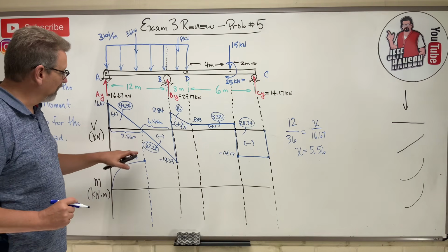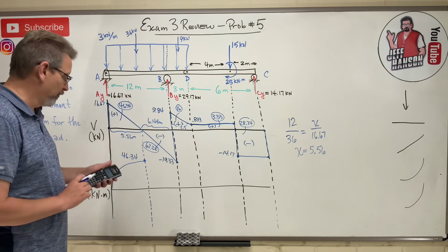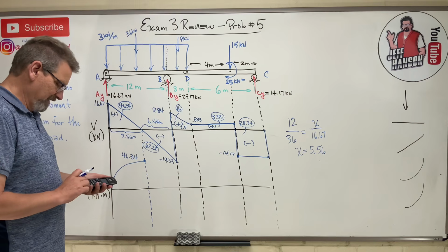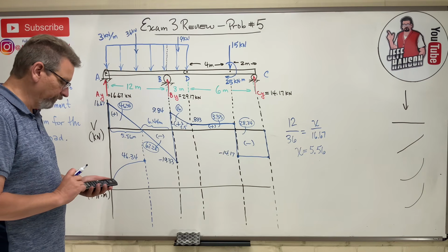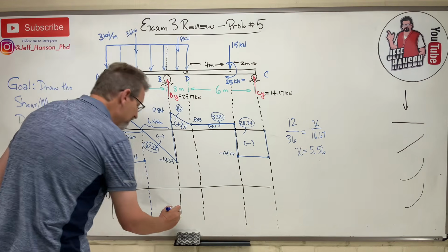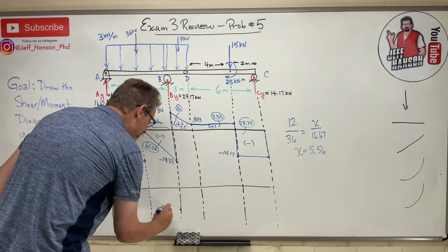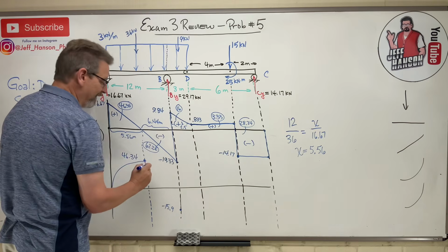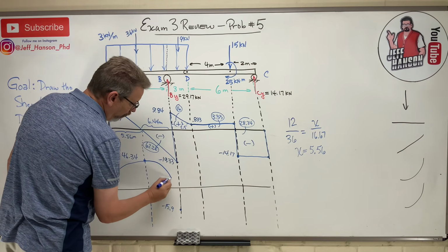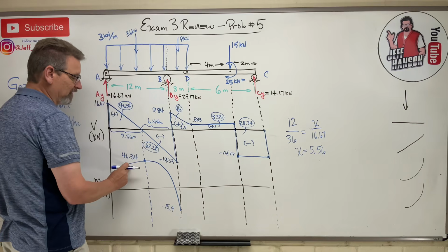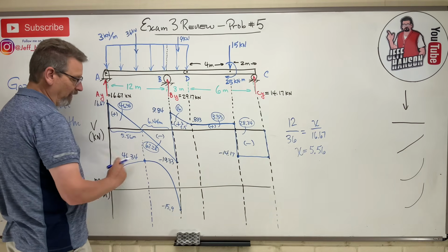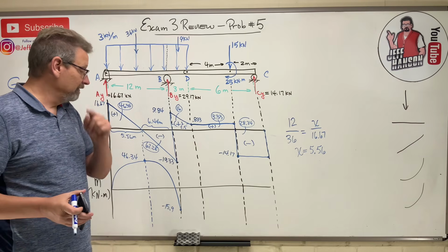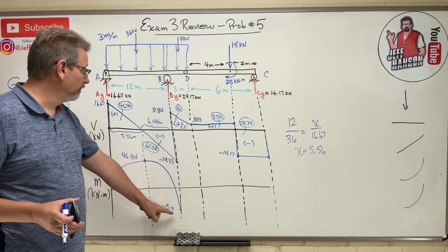Now the next section, I've got to go down 62.24, but I'm at 46.34, so 46.34 minus 62.24 equals negative 15.9. So that takes me down to right there, negative 15.9. And how do I get there? Slow, then fast. So kind of almost flat and then whoop. And the inflection of these curves, this way versus that way, is probably the most missed thing. So remember the slow-to-fast, fast-and-slow trick. It's very good.